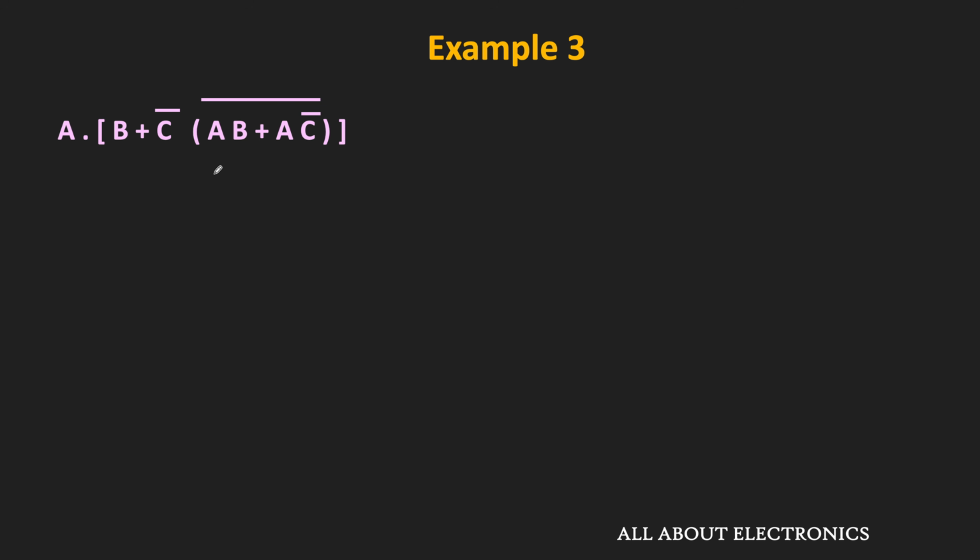So as you can see over here, this expression in the bracket has a bar on top of it. So in this bracket, we will apply the De Morgan's law and then we will simplify this expression. So first of all, let us write down the remaining expression as it is, that is equal to a dot b plus c bar. Now in the bracket, what we will do? We will give the bar to each group and then we will change the sign. That means we can write this bracket as (a dot b) whole bar dot complement of the a c bar.